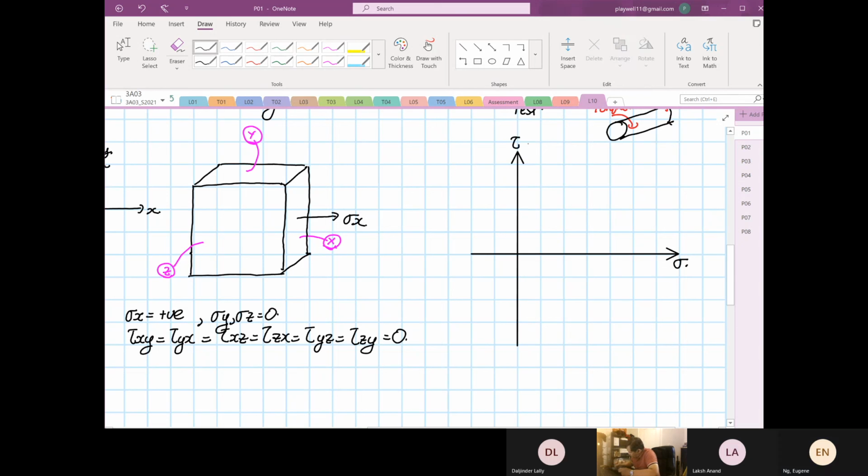and then you have your shearing stress. Element rotates clockwise, element rotates anti-clockwise, and then we know stress Y and stress Z are on the shear line, and we are also aware that this will be our stress X. So for this case, this is our point X, and you can see for the first time that a 3D Mohr circle can be a single circle in this condition.